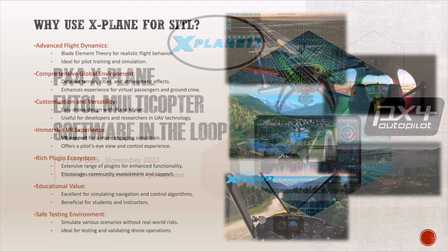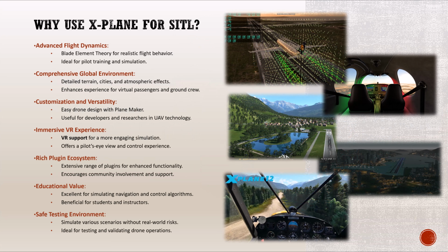Let's talk about why X-Plane is such a great choice for software in the loop. Well, maybe not the best choice for all applications, but let's find out in which applications it stands out. First up, X-Plane's advanced flight dynamics are based on blade element theory, which gives you a realistic initial flight behavior without knowing much about your drone or doing any sort of modeling or CFD analysis beforehand. This is perfect for initial design steps of many drones, especially air taxis and heavy eVTOLs.